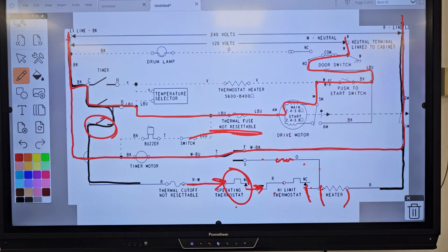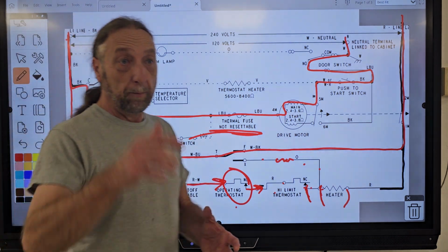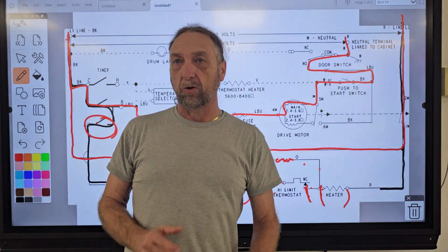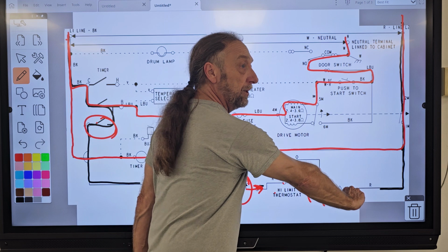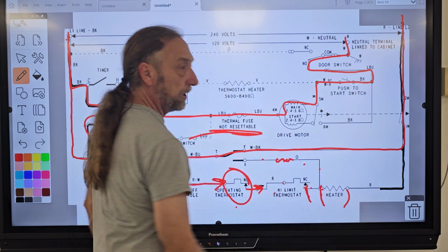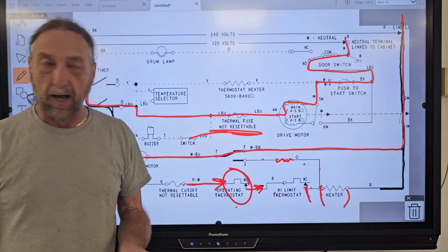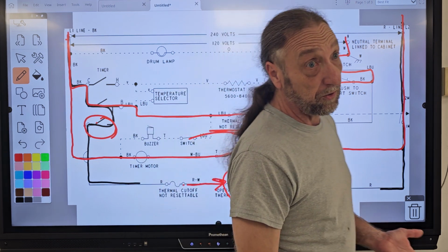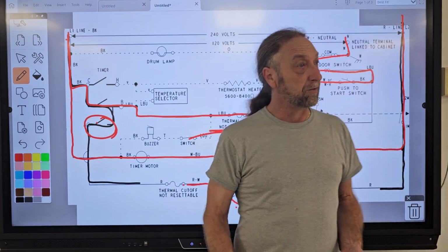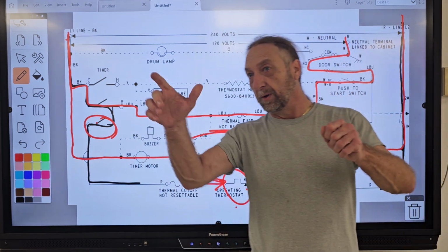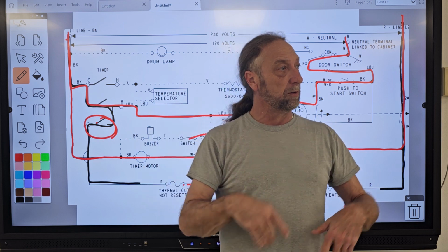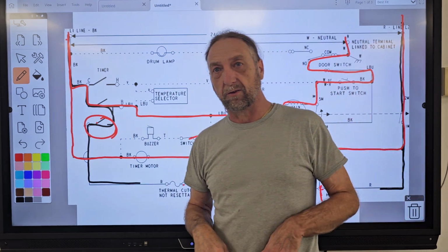And when we're troubleshooting, we want to have one meter lead. That's why alligator clips are good, because I can clip one meter lead here and just move the other one, clip it, turn the machine on. Now, in the competition, you should do this in the customer's house too: you unplug the machine, move your meter leads to your next test point, plug it back in and do the test.